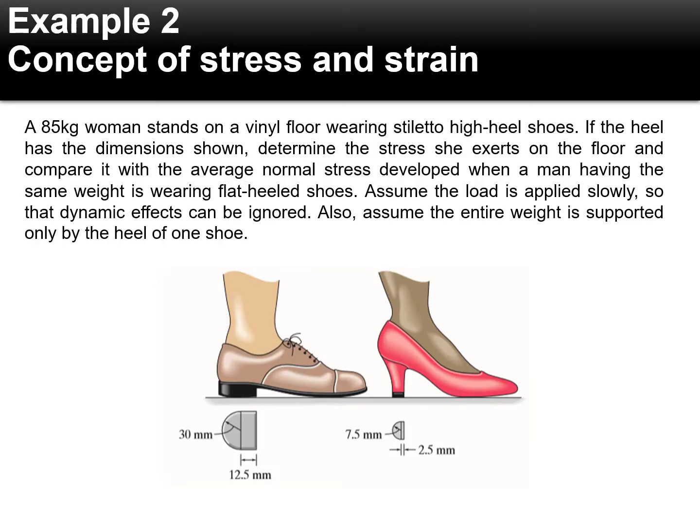Okay, so another example: an 85 kg woman stands on the vinyl floor wearing stiletto high heel shoes. If the heel has the dimensions shown, determine the stress she exerts on the floor and compare it with the average normal stress developed when a man having the same weight is wearing flat heel shoes. You need to assume the load is applied slowly so that the dynamic effect can be ignored. Also assume the entire weight is supported by the heel of one shoe only.